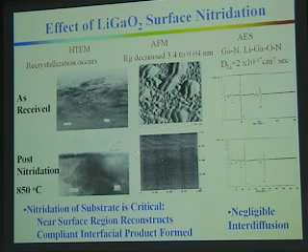So that surface chemical composition was a lithium gallium oxynitride, and we estimate about 15% nitrogen. But this recrystallization was probably a key step to being able to grow high-quality gallium nitride. And this oxynitride being a compliant substrate relative to the underlying lithium gallate was also important for the growth of high-quality gallium nitride.